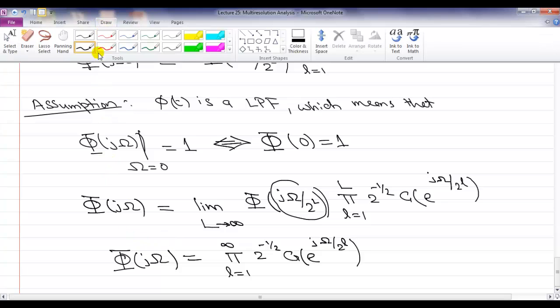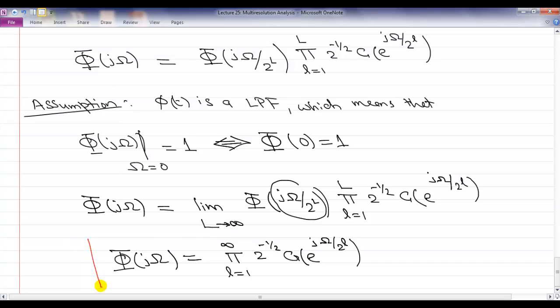So this is one of the most important relationships that we use to, for example, come up with scaling functions. We'll study more properties of the sequence g of n. What effectively happens is that you start your multi-resolution analysis not with phi of t, but rather with a filter g.